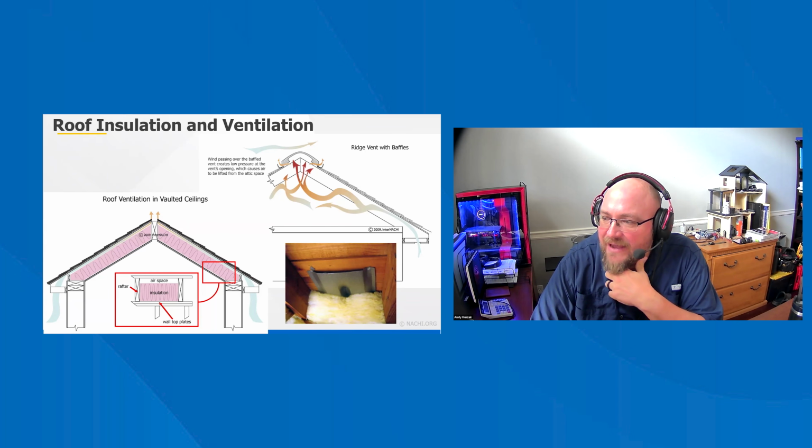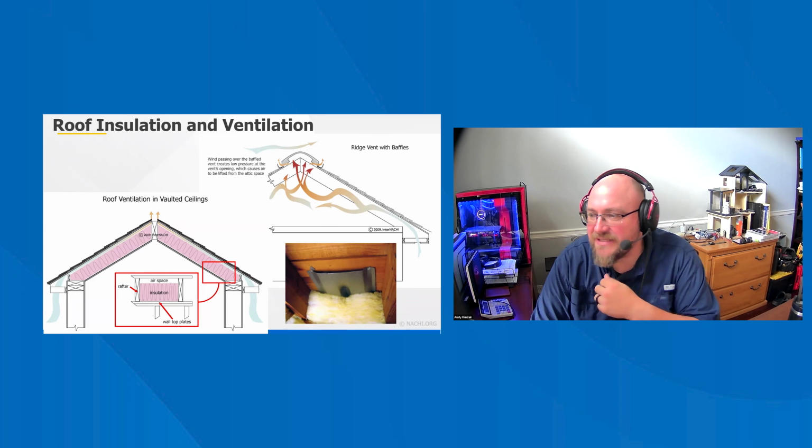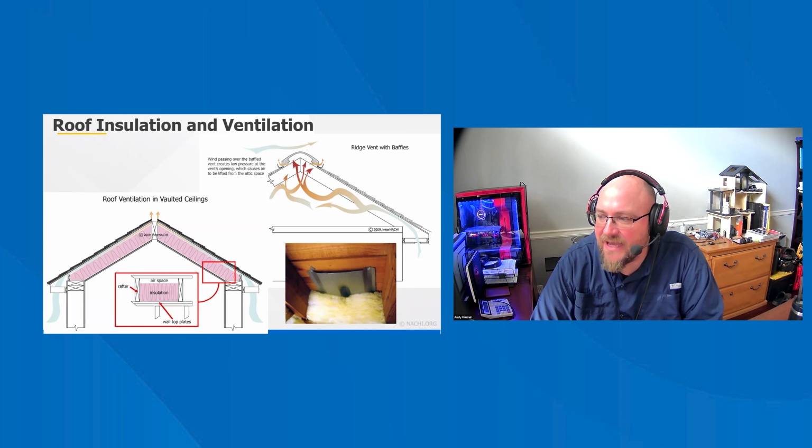When the rafter vents or baffles are in place properly, the batts or blankets or blown insulation can be installed right out to the very edge of the attic floor. Blown insulation may require an additional set of rafter vents or blocking material to prevent the insulation from being blown into the soffit. A piece of rigid foam board placed on the outer edge of the top plate works very well for this purpose.